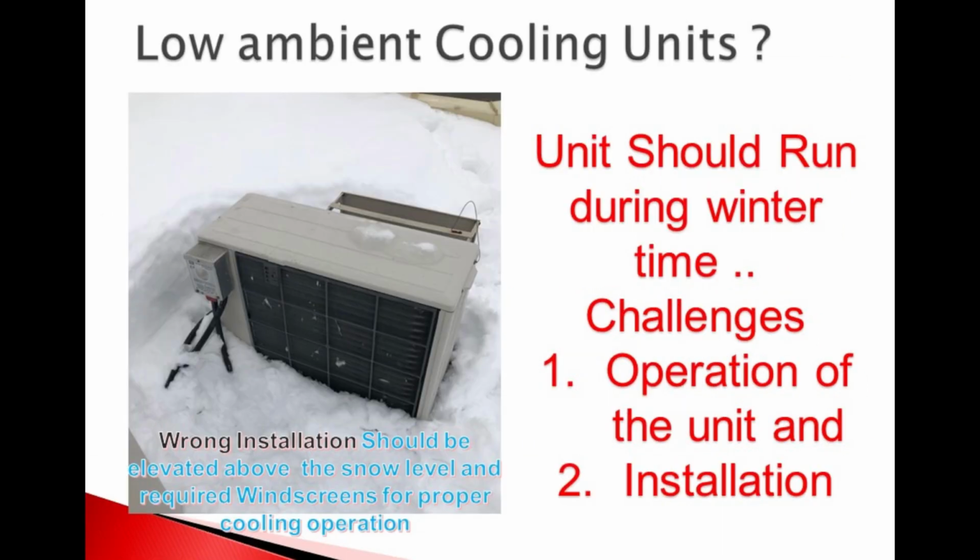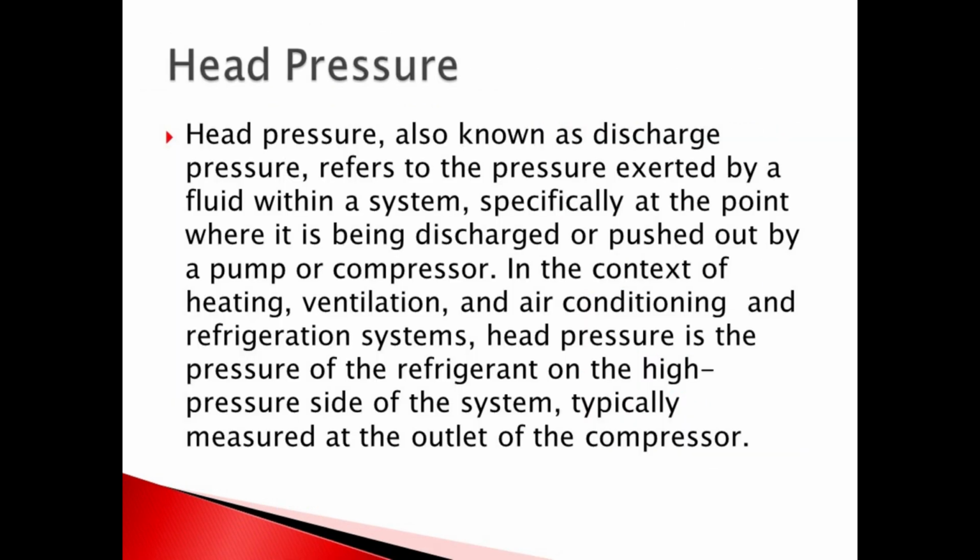To understand how low ambient cooling units work, imagine you are tasked with designing one yourself. Start by considering the specific challenges and requirements that come with creating a cooling unit that operates efficiently in low ambient temperatures. During wintertime, outside temperature is very low and the compressor has to work very little. Power input required is very low. But one major issue is maintaining head pressure.